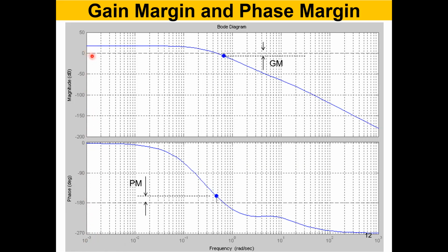But now it's slightly above 1, so there's a net amplification of the signal for some frequencies. Then around 0.3 radians per second, gain reduces, and after that, as you increase the frequency, the magnitude drops.